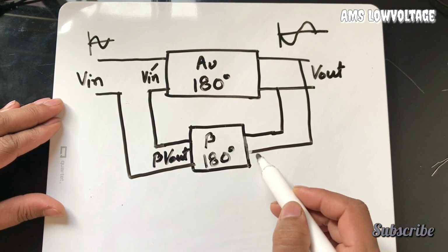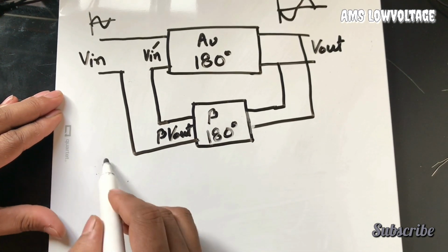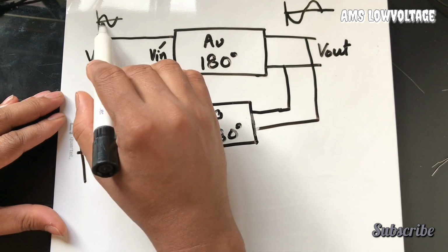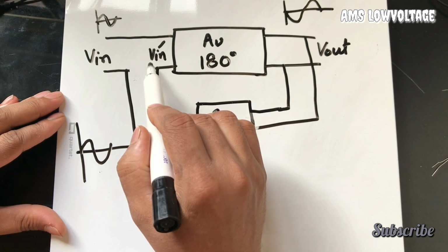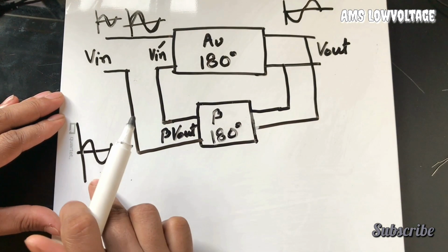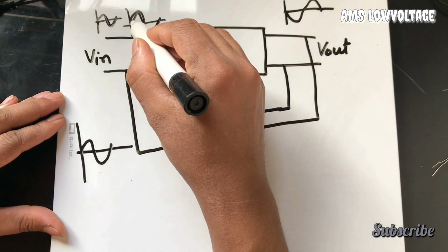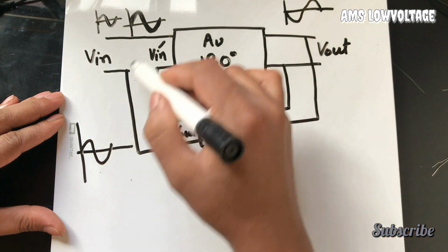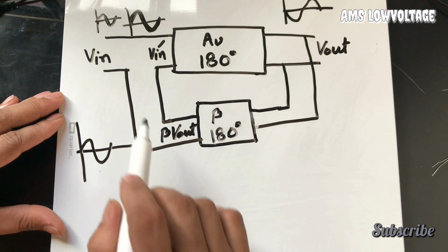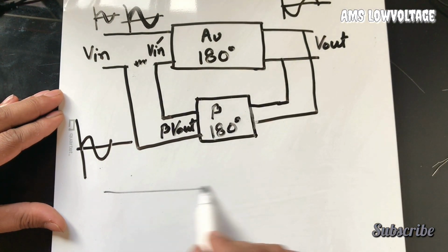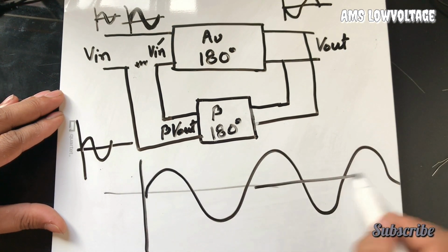And when this signal again passes through this positive feedback loop, it will convert again just like this input one. So when this converted positive feedback loop signal comes with the phase shift to the amplifier's input, the input signal will be reinforced a little bit. This signal will push the original signal and make it a little bit more powerful and fed to the amplifier. And when this procedure happens again and again, once a little disturbance happens in the input like this, the whole circuit will start the oscillation by itself, and it will never stop if you do not stop it.